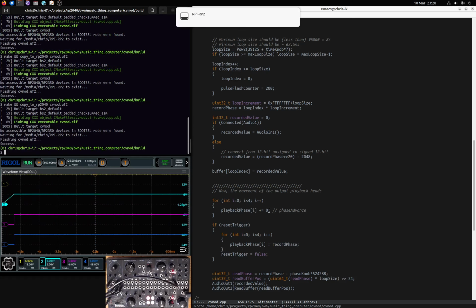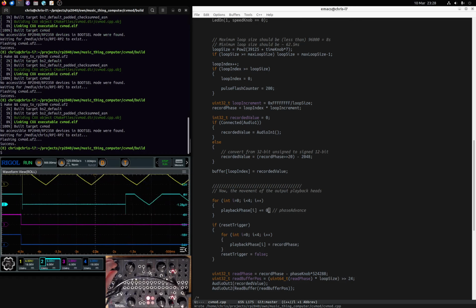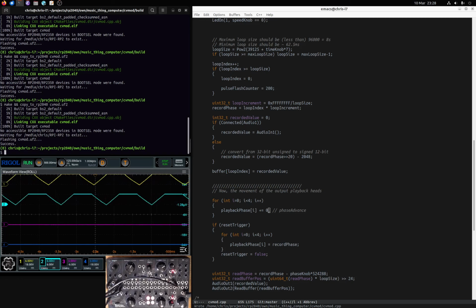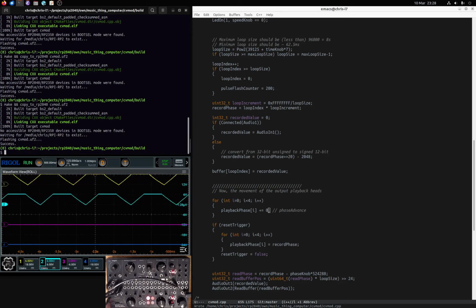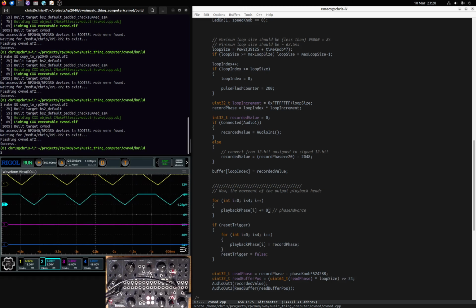So what we're hoping to see now is when I turn the knob, yeah, okay, that looks good. When I get it at 12 o'clock, that top LED lights up, but it doesn't when I'm away from that. Okay, fine. So we've now got the speed knob, which can either be exactly 0 or some position that isn't 0. But when it's exactly 0, ooh, I must be right on the edge of it there. Okay, it might even benefit from adding some hysteresis to that at some point.